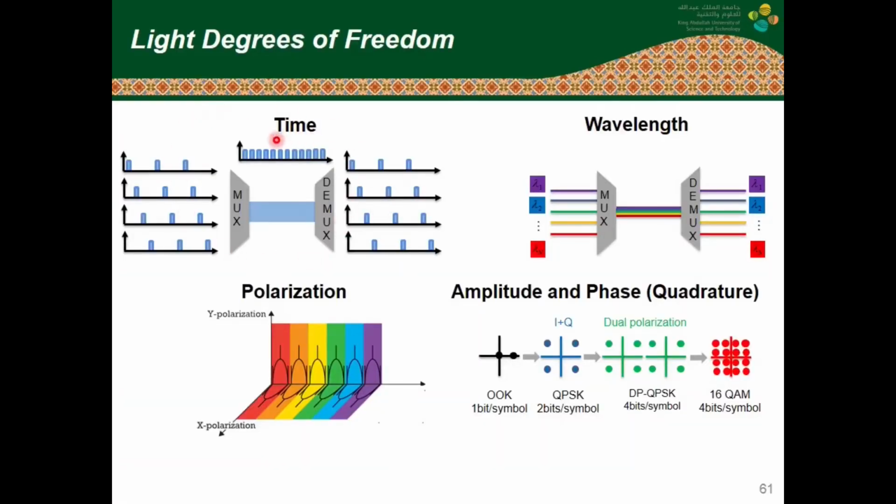In optical communication, different signals can be sent over different time slots through the well-known time division multiplexing scheme. Independent data signals can be encoded on two orthogonal polarization states, which can double the capacity of a transmission system. It is also possible to encode different data streams on different wavelengths, which scales the capacity by the number of the used carrier frequencies. Data can be further encoded using advanced and complex modulation formats.